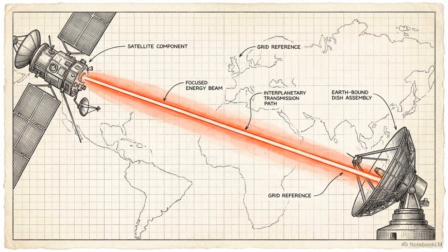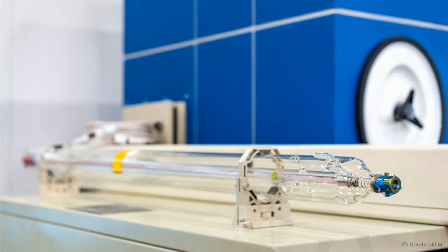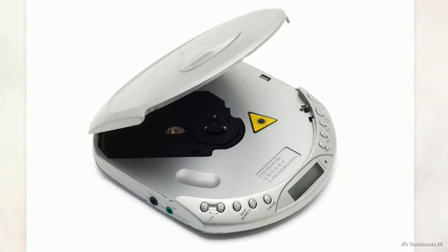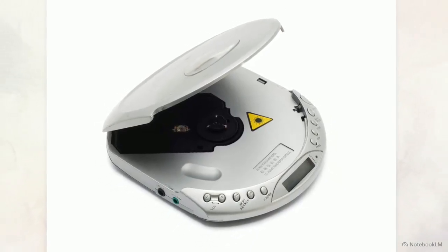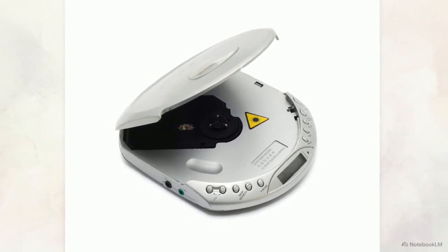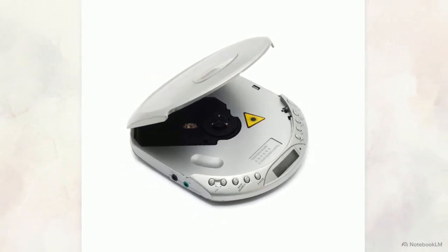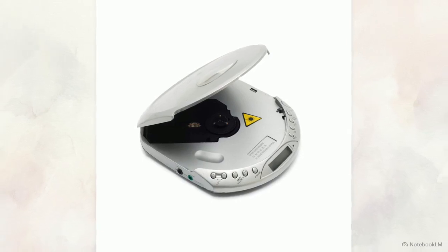physical structure. While the hardware triad remains constant across designs, changing the specific material used for the gain medium alters the laser's physical output and industrial purpose. Solid-state lasers, using materials like ruby crystals, and gas lasers containing helium-neon or carbon dioxide, deliver extreme thermal power for high-precision operations. Semiconductor lasers, or diode lasers, rely on miniature components. Their small physical footprint makes them the standard for integration into everyday consumer electronics.